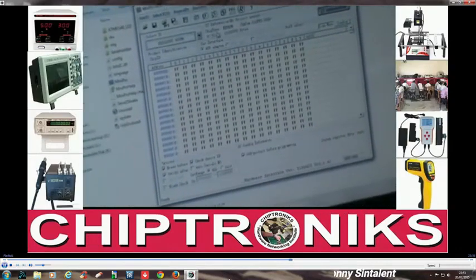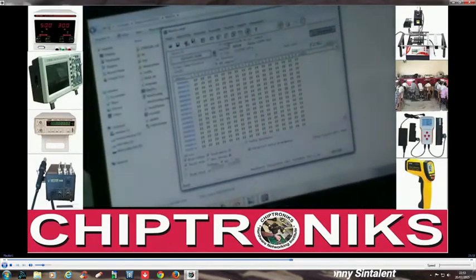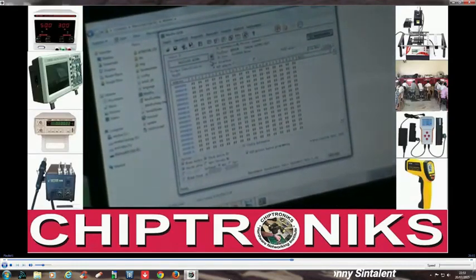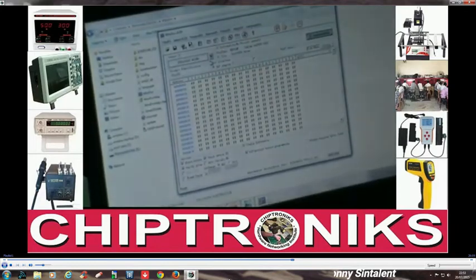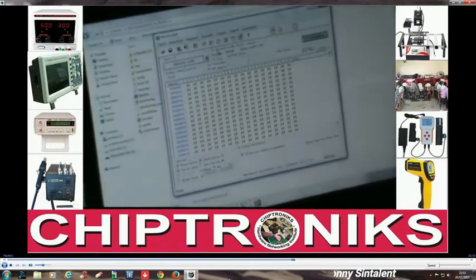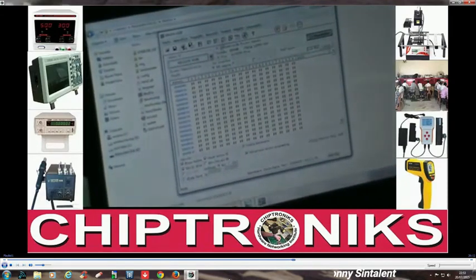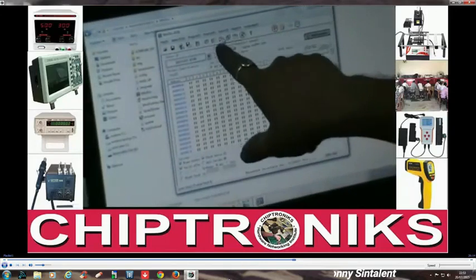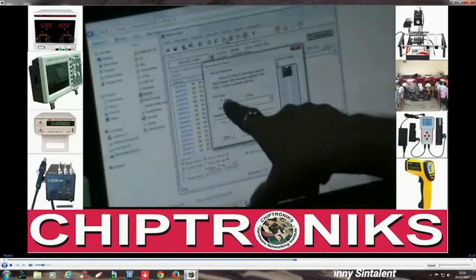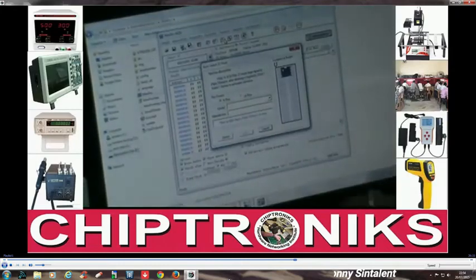This is the software. Now here you see this BIOS programmer has a good facility for auto detection. No need to read the number, you just go over here, auto 25 select. This facility is only for 8 leg IC and 16 leg IC.